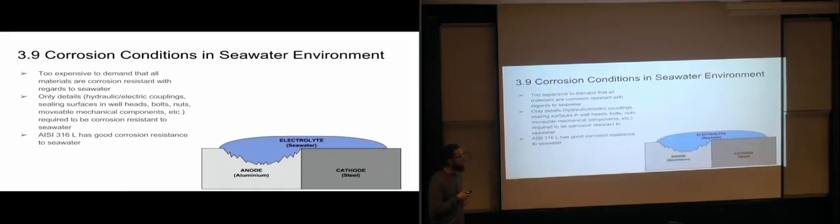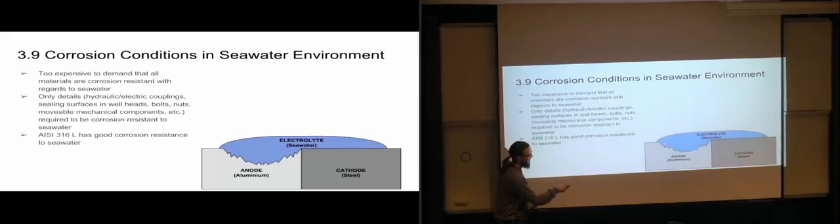And when we're looking at seawater corrosion, we are especially looking at different materials that will be corroding each other. So for an example, if we have aluminium and steel combined together in one design so that they are in contact with each other electrically and also in contact with seawater, both of them, then what's going to happen is that the aluminium is going to become the sacrificial anode and the steel is going to become the cathode. So basically we're going to start dissolving the aluminium. So the seawater will start eating away at the aluminium.